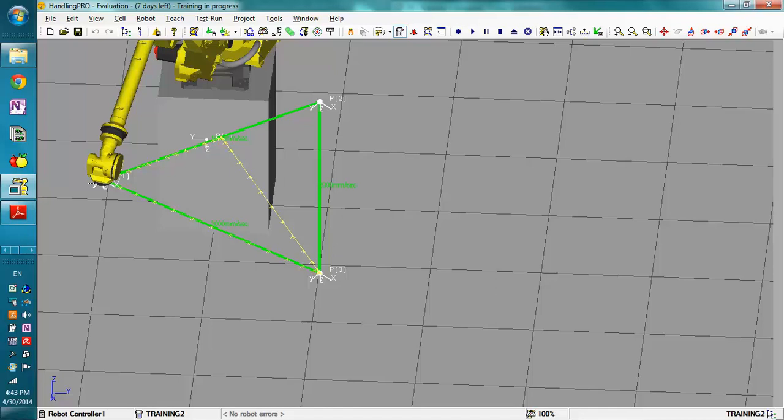Mostly, I see the skip condition used to stop a motion when the robot senses a part. So if the robot's going to a pick position and senses the part, it usually stops motion, saves the position, and then moves backwards.